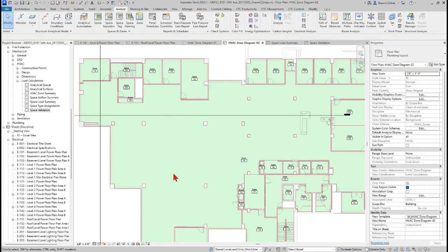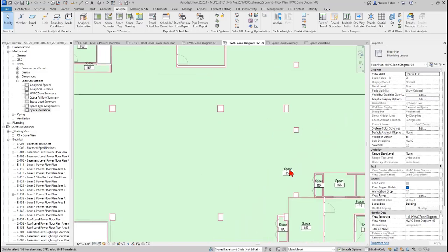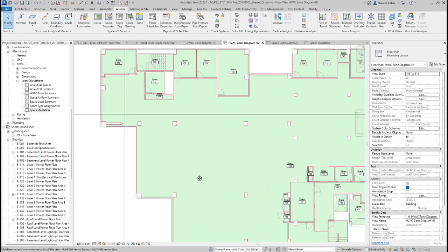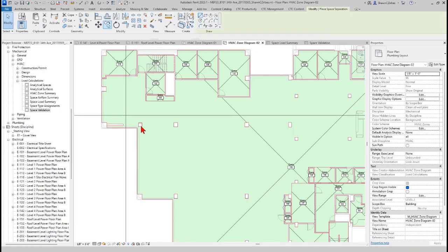And I'm going to do this intentionally before I take you through the space renaming little step here, because I want the space to match whatever the architect's space name is. I want the number probably to match whatever their number is, but I don't want to necessarily have this be all one big old space. So I'm going to do some space separation here.